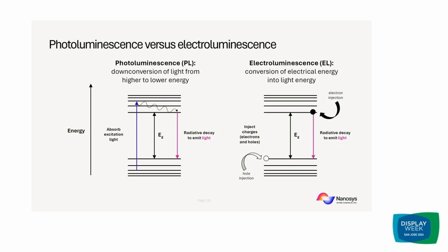So again, moving to the highest level of that roadmap that I was showing earlier, the two lower levels were photoluminescence and then photoemissive, so direct on pixels. The highest category of application you could have from quantum dots is direct luminescence, electroluminescence from the system. Schematically, going back to these energy diagrams, in photoluminescence, a high energy photon comes in, creates your excited state, and then radiative decay emits your light.